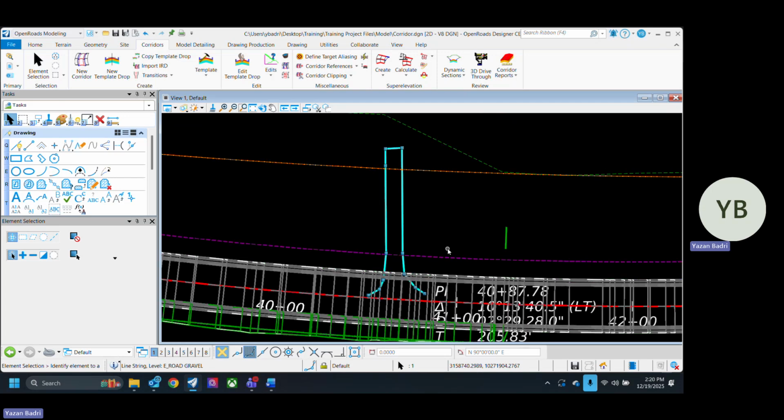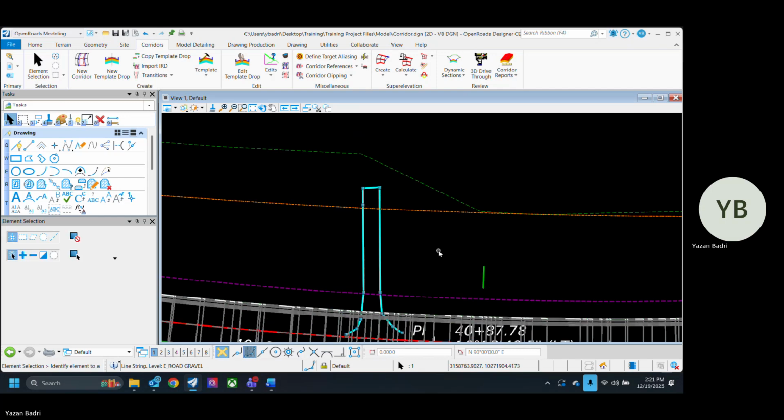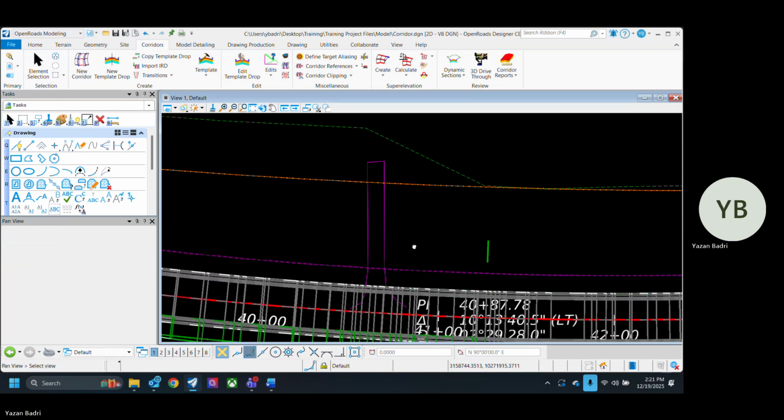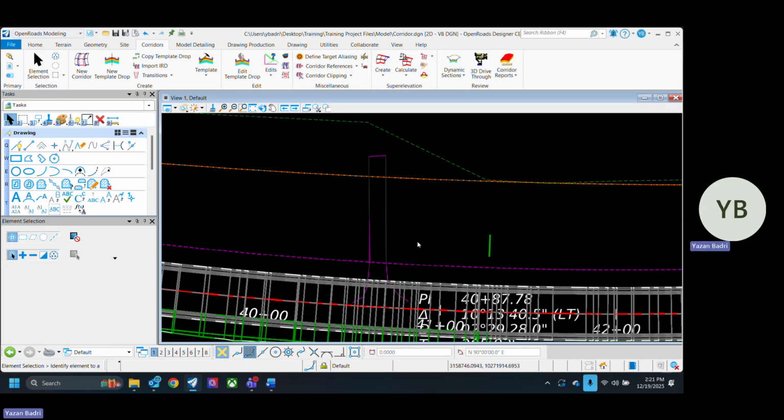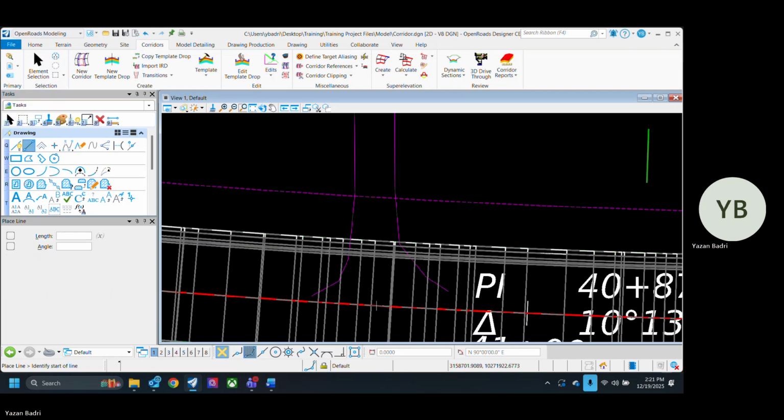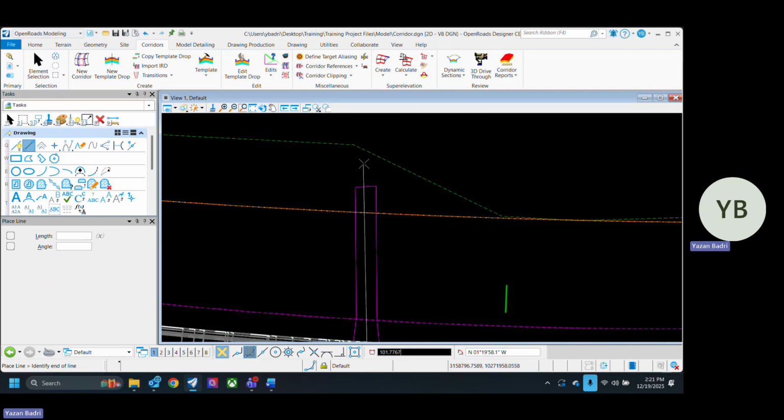There's two ways to do the driveway, either manual grading, which I'm going to do, and there's the corridor. Both of them need a significant amount of effort to get. So first of all, before doing anything, I want to fix the geometry of the driveway to make it like an actual driveway. So first, I'm doing this quick. So I'm just going to draw a center line for this driveway.